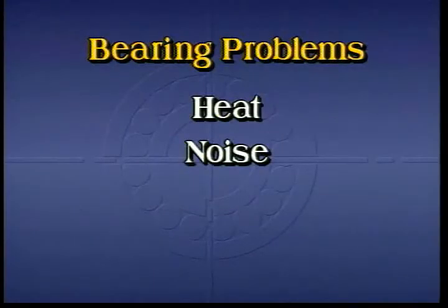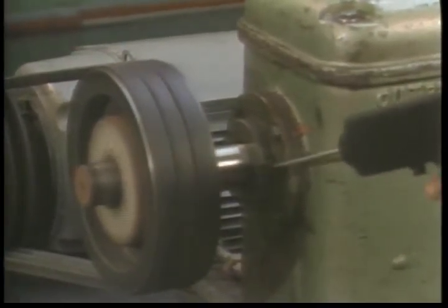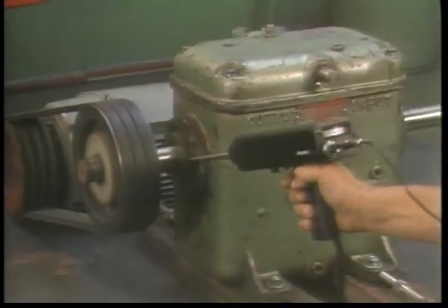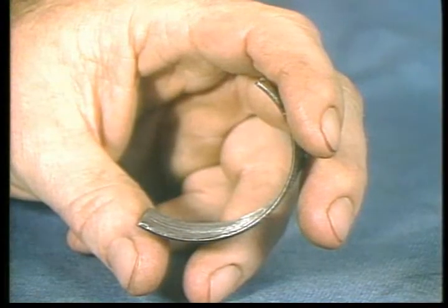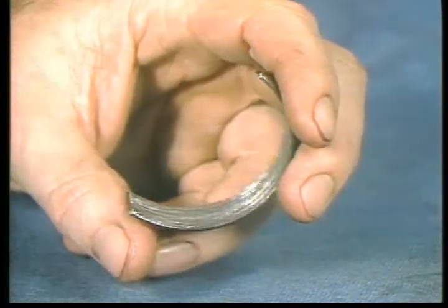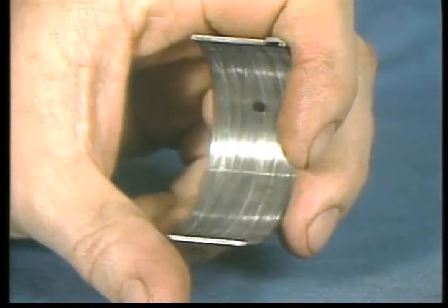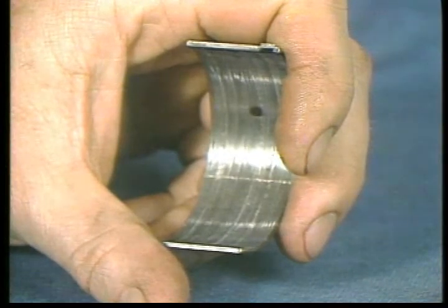You should also listen to the noise the bearing makes. Sounds will often indicate the bearing condition. Experience can help because you can become familiar with specific machine sounds, or you can compare sounds to those in similar applications. In a plain bearing, knocks and thumps are an indication of slackness. With a constantly changing load direction, these noises will be naturally loud and easy to detect. The sound can also indicate excessive end play or end float in the shaft.